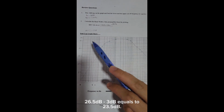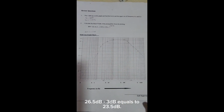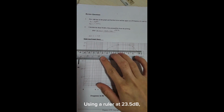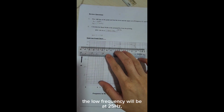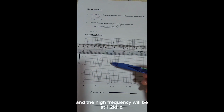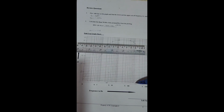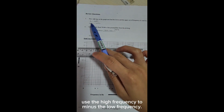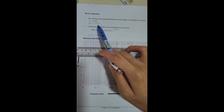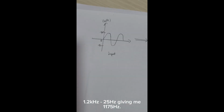On the frequency response curve, the minus 3 decibel line will be 26.5 decibels minus 3 decibels equals 23.5 decibels. Using a ruler at 23.5 decibels, the low frequency will be at 25 Hz, and the high frequency will be at 1.2 kHz. To find the bandwidth, use the high frequency minus the low frequency, 1.2 kHz minus 25 Hz, giving me 1175 Hz.